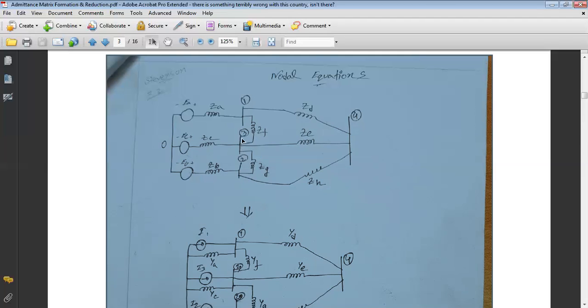It means that if we want to put bus number 2 here, then the connection should be changed, because from bus 2 there should be 3 connections. So we have to maintain the 3 connections here if we want to renumber the buses. And if we put 3 here, then we have to put 4 connections here.